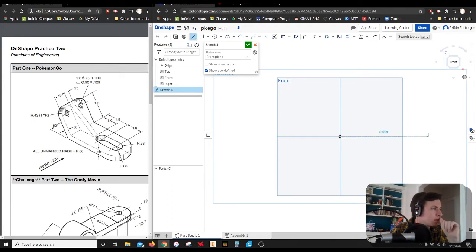And I'm going to start by drawing a line that is 3.38 in length. Oh, I will dimension it after actually. And then I will draw this one up over here. Cool. So let's dimension this line, and like I said, it's 3.38, and we find this by adding up the lengths over here. So we've got 1.5 plus 1, so we're at 2.5 plus 0.88, which is our distance from the center all the way to the edge. So we get 3.38 for our total length.